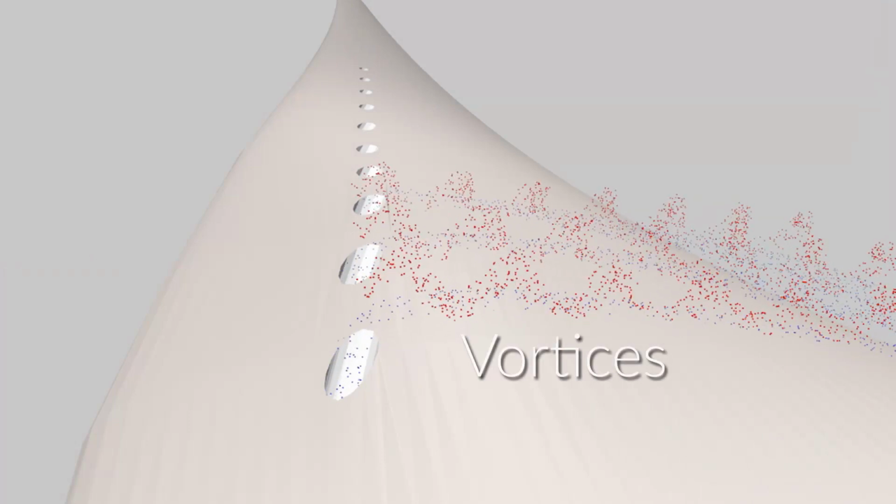So the idea was to take air jet vortex generators, which are similar to vanes when you look out the window of an aircraft and see these vanes sticking up in the air above the wing. The idea is to blow air out, train a vortex around that air that was ejected, and that would re-energize the boundary layer of the wind turbine.